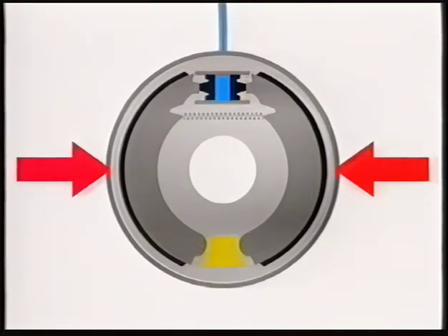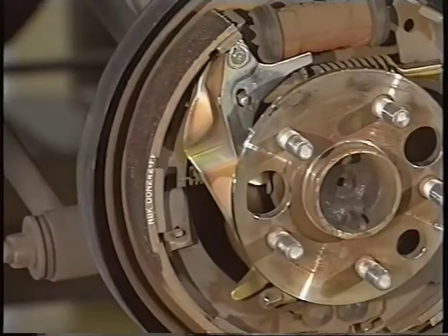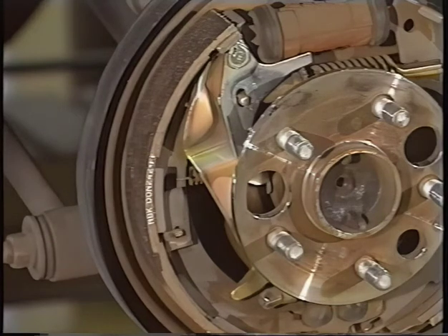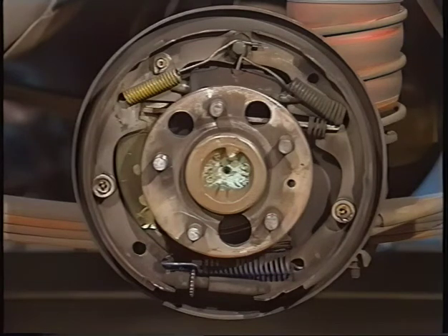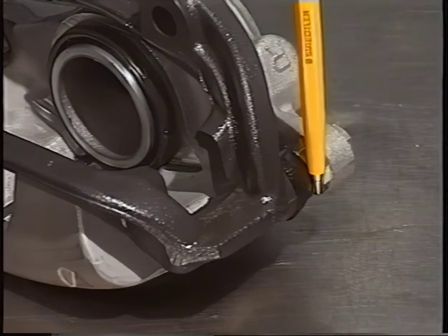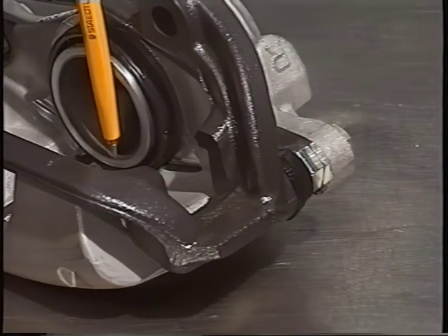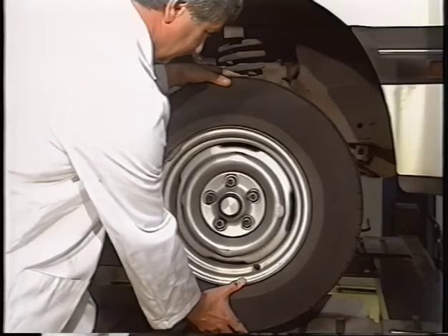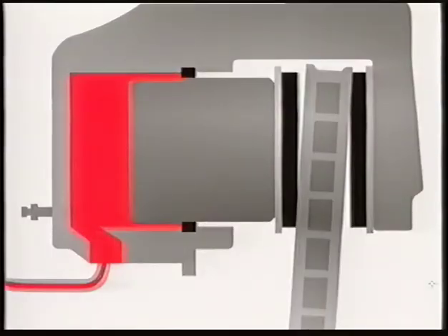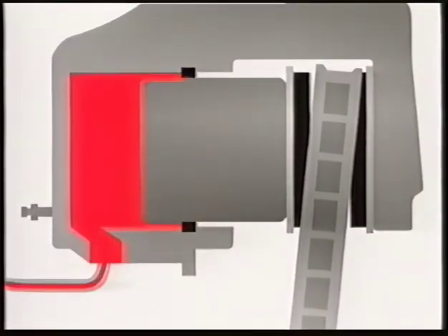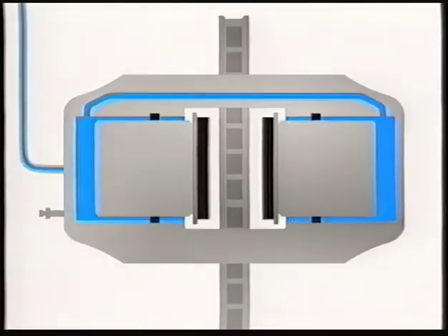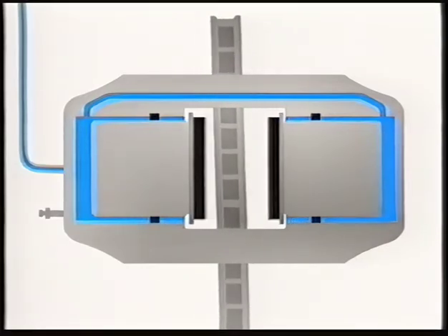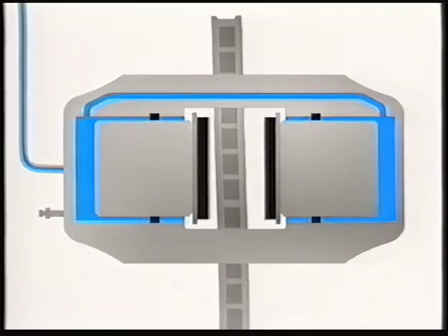Excessive clearance between the shoes and brake drums leads to low brake pedals. This is usually caused by self-adjusting mechanisms being either seized, incorrectly adjusted, or having been removed at some stage during the vehicle's life. Disc brakes, on the other hand, may suffer from seized caliper slides and pistons, or excessive free play in either front or rear wheel bearings. With the first condition, the disc is progressively deflected a greater distance as the pads wear, causing the increased pedal travel. Whilst in the second case, of loose wheel bearings, the disc knocks the pads back further than they normally retract.